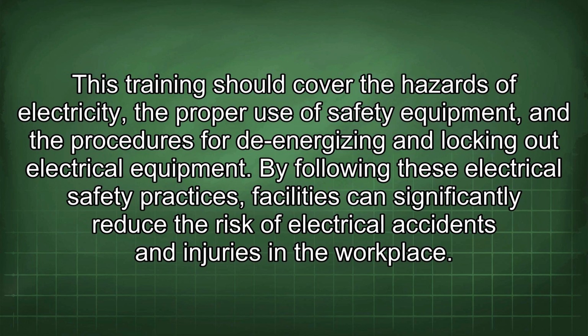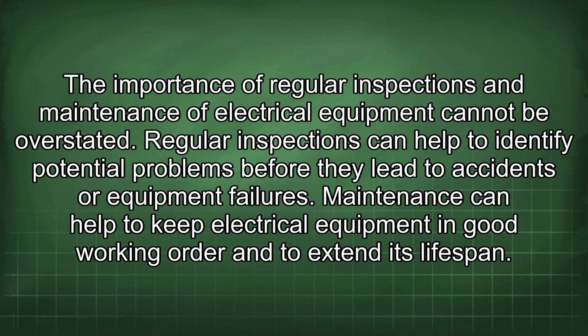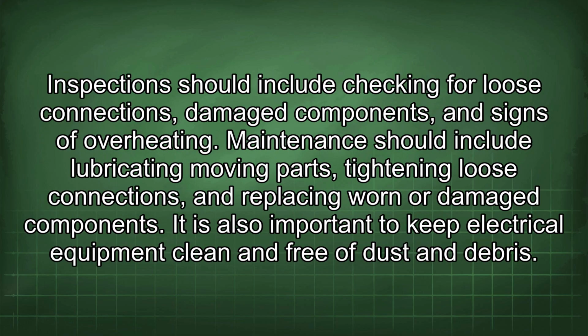injuries in the workplace. The importance of regular inspections and maintenance of electrical equipment cannot be overstated. Regular inspections can help to identify potential problems before they lead to accidents or equipment failures. Maintenance can help to keep electrical equipment in good working order and to extend its lifespan. Inspections should include checking for loose connections, damaged components, and signs of overheating. Maintenance should include lubricating moving parts, tightening loose connections, and replacing worn or damaged components.